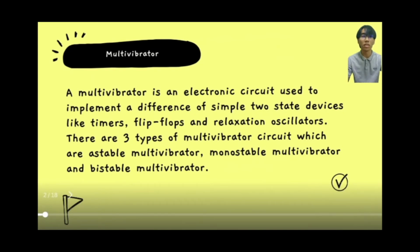For the multivibrator, what is a multivibrator? A multivibrator is an electronic circuit used to implement a variety of simple two-state devices like timers, flip-flops, and relaxation oscillators. There are 3 types of multivibrator circuit, which are astable multivibrator, monostable multivibrator, and bistable multivibrator.